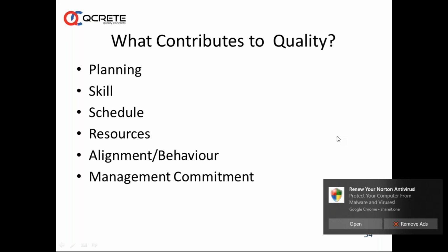For example, now the summer has started in India. You have summer temperatures maybe between about 30 to 40 degrees. If you are not taking care of the curing water temperature, 27 plus or minus 2 degrees, if the curing is done at elevated temperatures, in 7 days itself the reactions are faster, hydration is much faster, it might have achieved already 95 to 100%. There may be limited gain after 7 days.